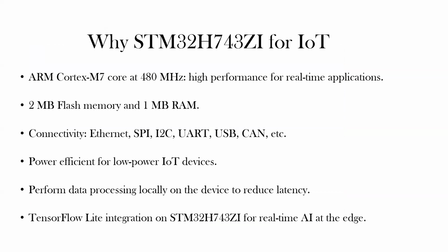Okay, now coming to our hardware. We have developed some prototypes using different microcontrollers. The reason why I chose the STM32 H7 series: H7 is a high performance series. This is one of the very high speed microcontrollers, which runs on 480 megahertz. And definitely with this speed, we can meet the deadlines in real time